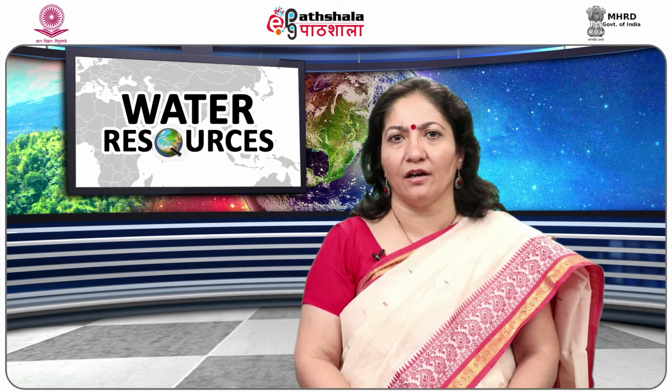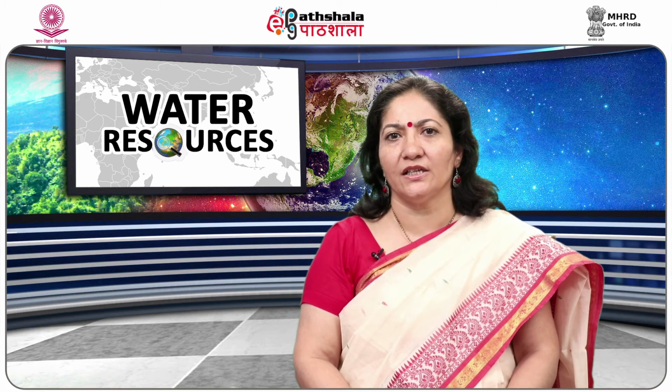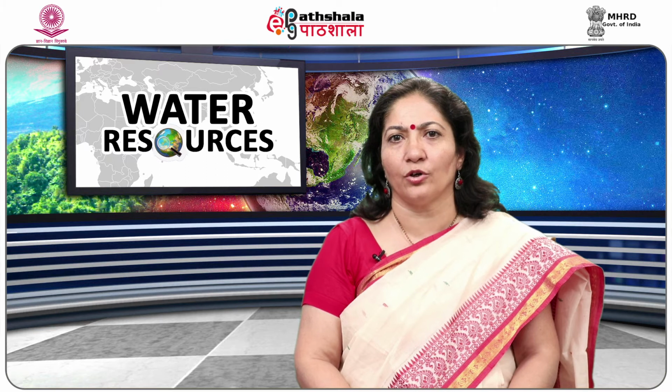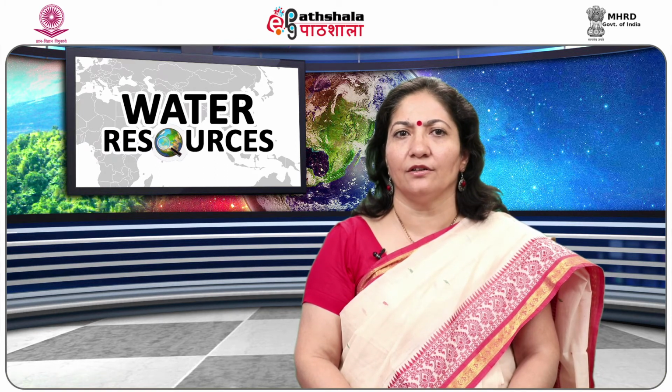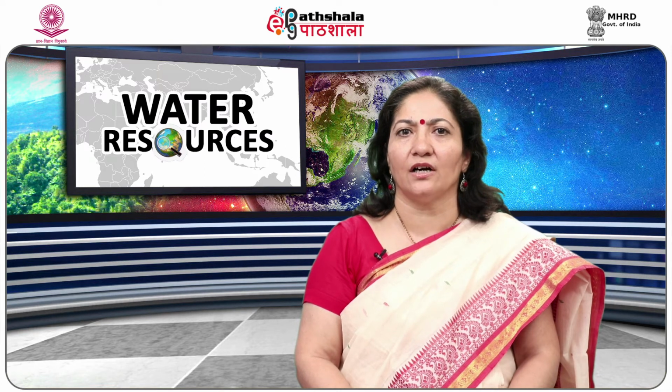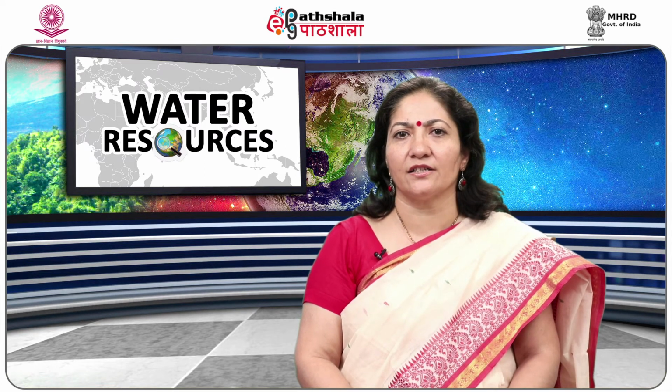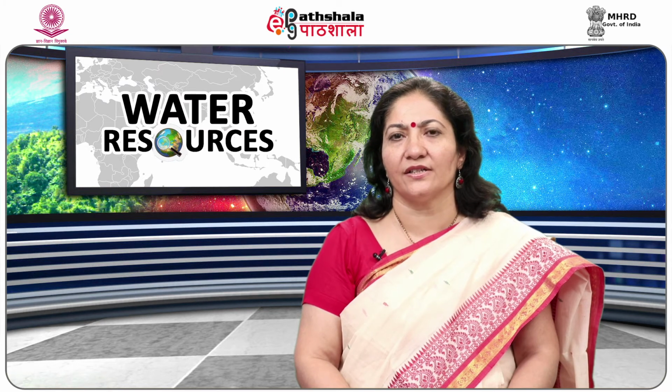Though clay and shale are porous and can hold a lot of water, the pore spaces within these fine-grained soils are too small for water to flow through them, except very slowly. Clay has low permeability due to small grain sizes with large surface areas and less connectivity of pore spaces. Sandstone and conglomerate are highly permeable due to the presence of large interconnected pore spaces between the grains. This is depicted in Table 1.3.